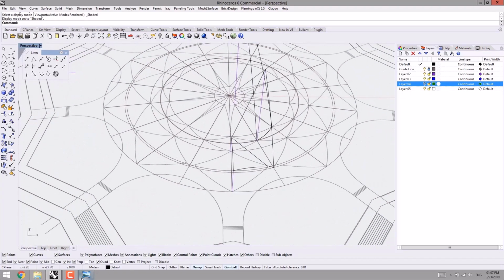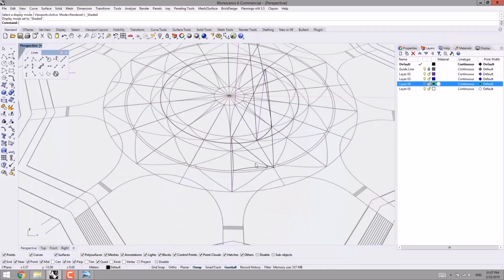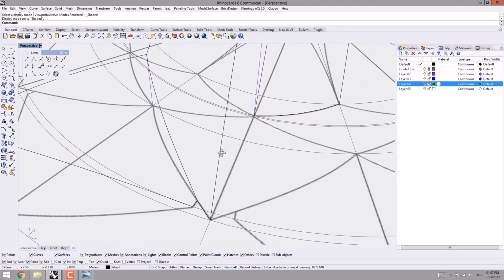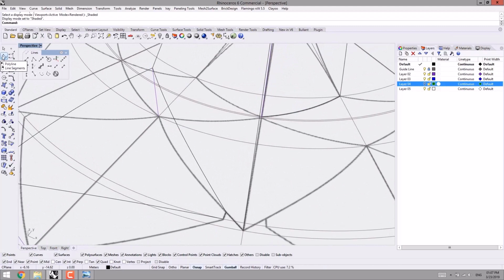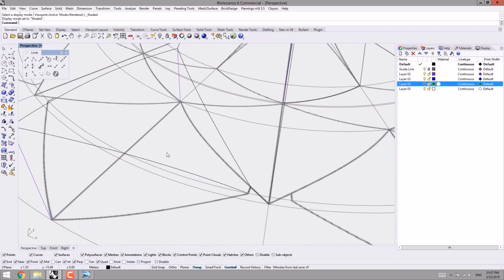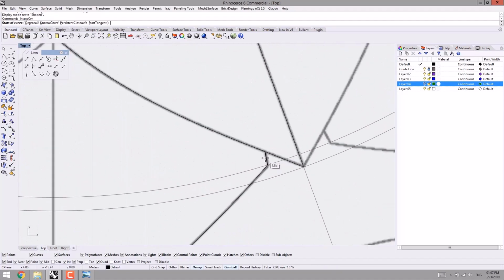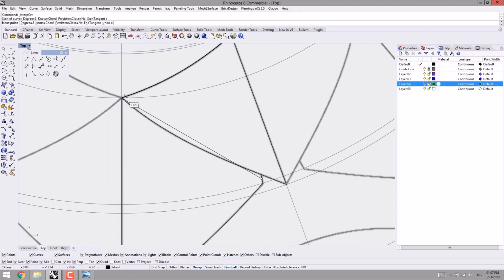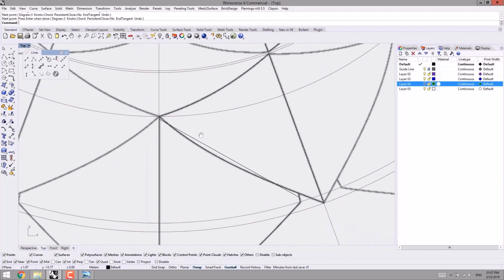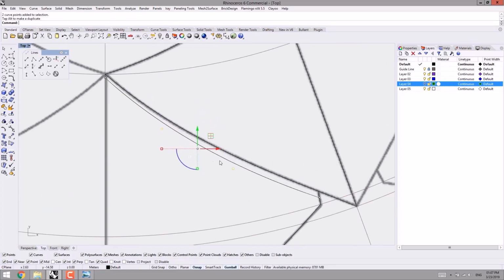And in the next stage, we're gonna create these windows or these storefront walls. So let me see. In Rhino, I wanna search for a line. Wait for a second. For example, curve interpolate point. Then in the top view, from the midpoint, I connect these 2 points to each other by this way, and then I select the control points to curve the line like this way.